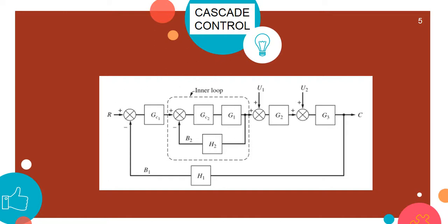We can make the overall transfer function, or rather we can derive the overall transfer function of this system, setting only one output to be related to one input change, even if we do not know exactly how the manner of controls happen with this inner loop within this outer loop. But we can derive, or you can use the principles that will be discussed here in terms of deriving the overall transfer function of the system, again relating one output to one input variable.